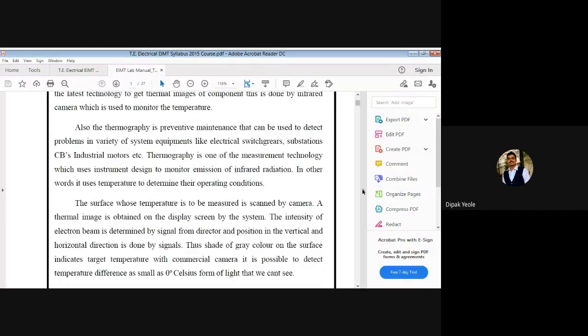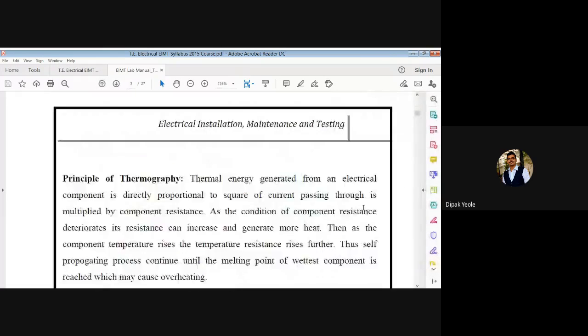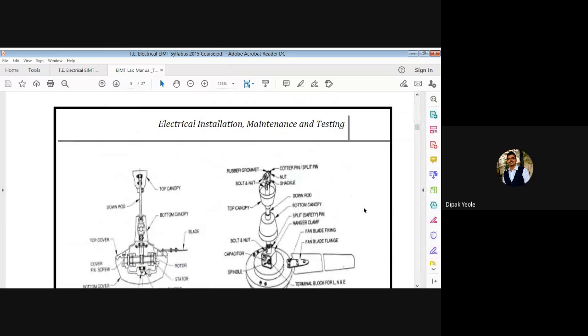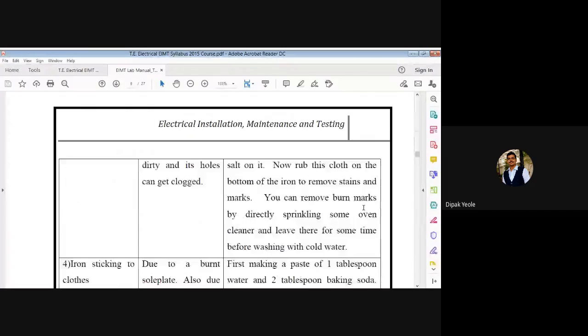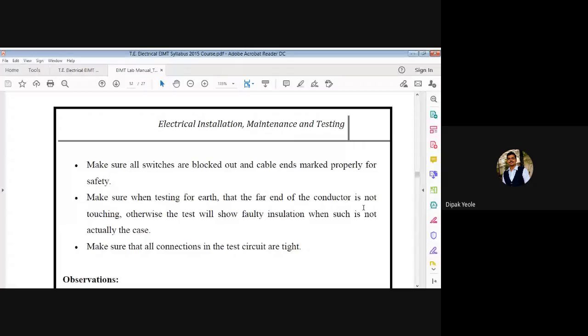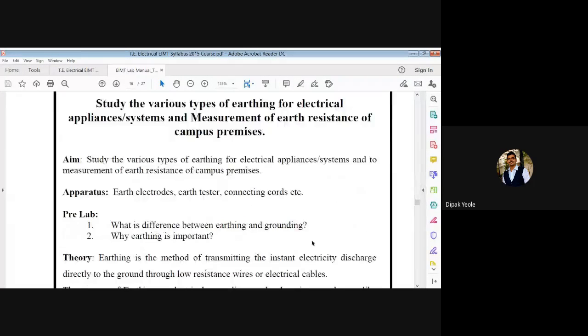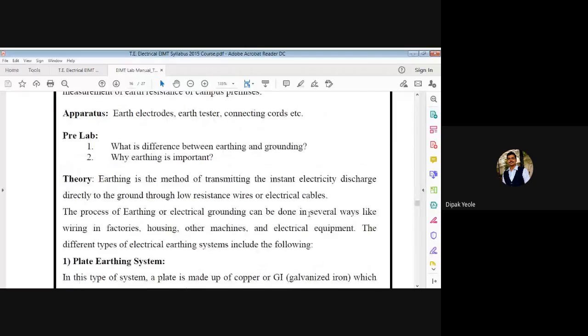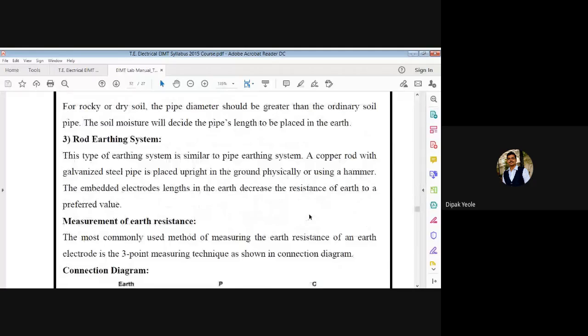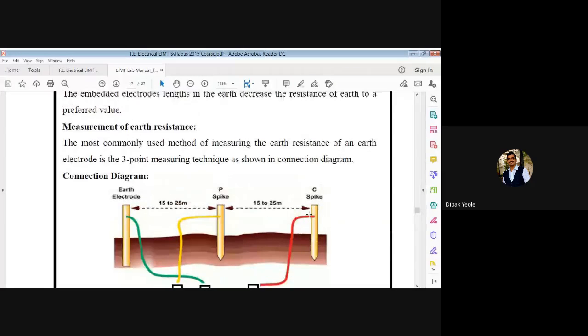Yes, and we have finished that whenever we are interested to measure with the help of a multimeter, the multimeter supplies its own value of voltage to that particular component, and because of that voltage the current is produced, and the ratio of V by I is responsible for measurement of that particular quantity. So that we have finished. Now in 2 minutes we will finish this experiment, and then we will start with the next experiment.